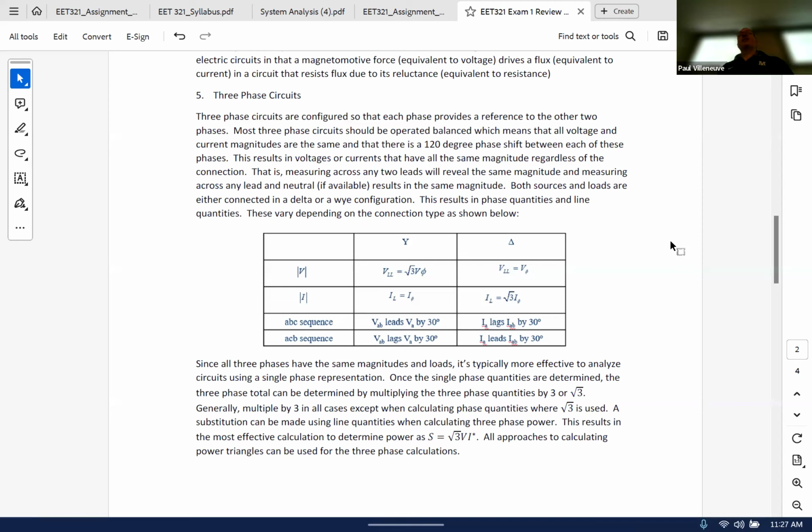If you get stuck, draw your phasor diagram, or just draw the diagram and see if you can see where the terms add together. It's usually easier to draw the phasor diagram, because when you do a connection diagram just showing the power supplies, you don't always see that 120-degree phase shift. So it makes it harder to represent that. So I always recommend just replacing your power supplies with a phasor diagram of the voltages or currents, and then you can add or subtract as necessary.